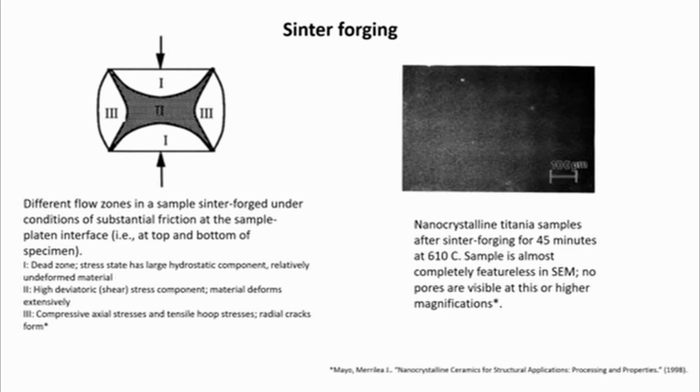Theoretically, there is no limit to how large a pore can be closed by plastic flow. However, it should be noted that a significant amount of plasticity is required. Strains around 0.62 by one theoretical calculation, but more is often needed in practice. Hence, only those ceramics which are superplastic, capable of deforming to true strains of 100% or greater, are able to take advantage of this mechanism.